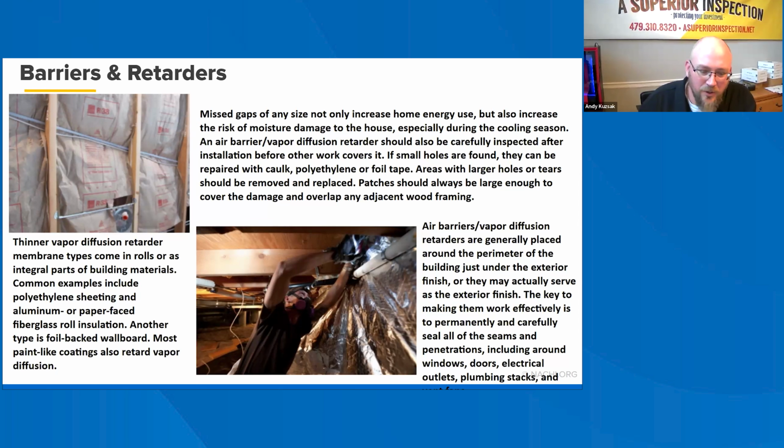Nobody could figure out why or where it came from. Everybody thought that there was a leak, but it turns out it was just condensation from the dew point on the trim because of the lack of a sill gasket. Because sill gaskets in my area are not required, interestingly enough.